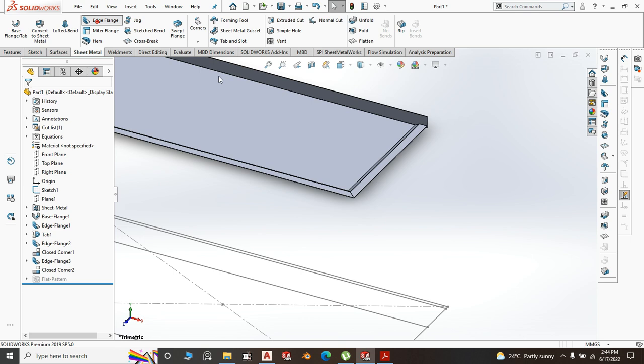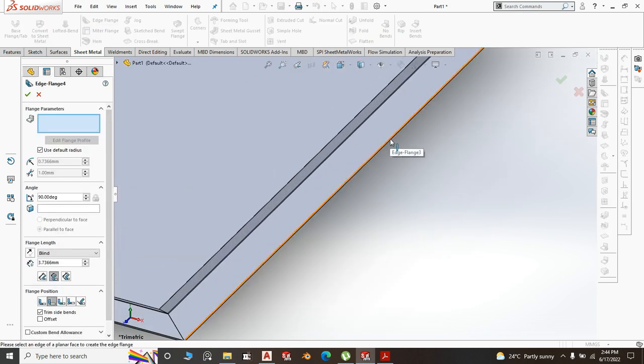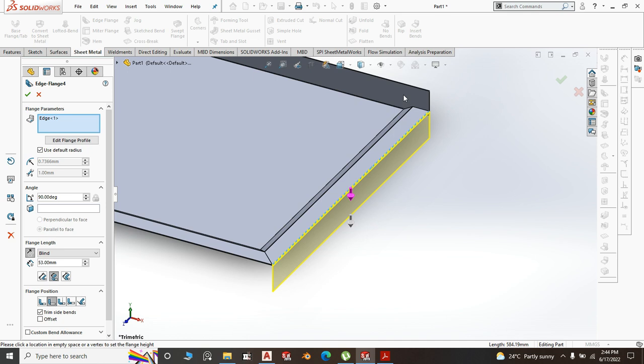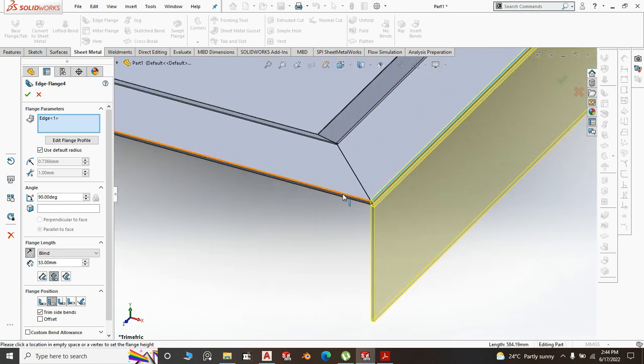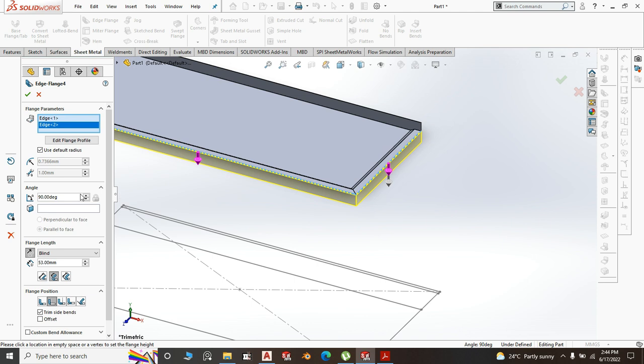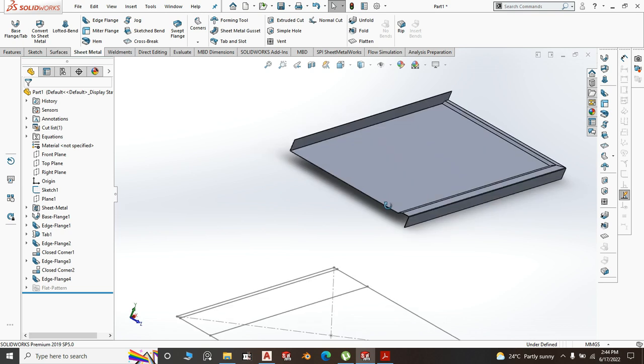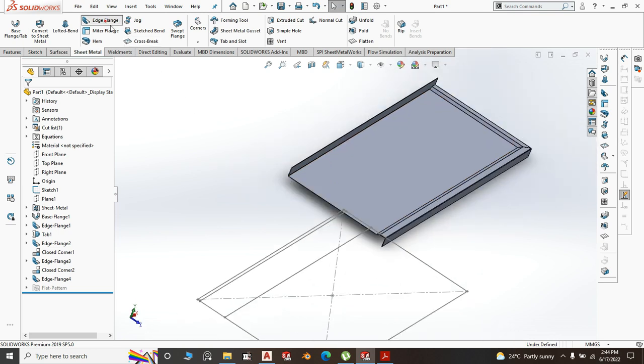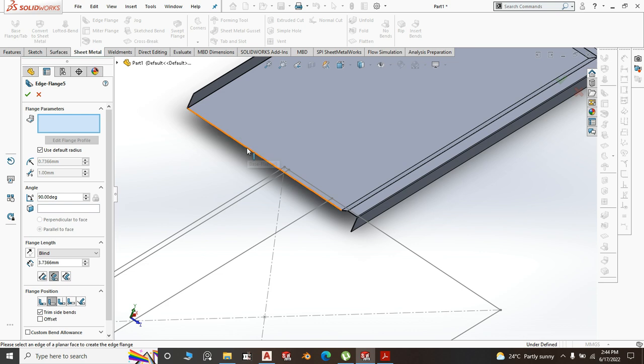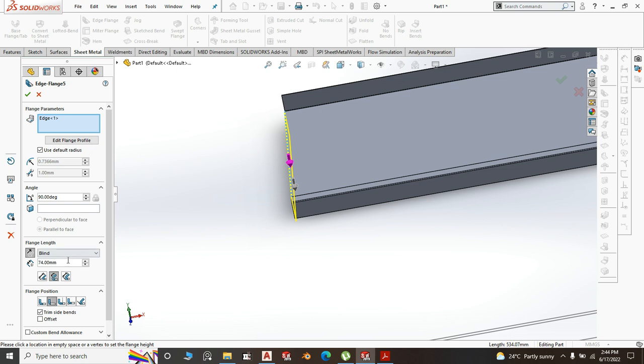Now create edge flange. Alternatively, you can do a mitre sketch and do all this flange at one go. Right, this, make it 50 and condition, right click. Then here is the profile where you're going to be hooking it to the dishwash sink. So you create an edge flange there which is 20mm by size, and that's okay.